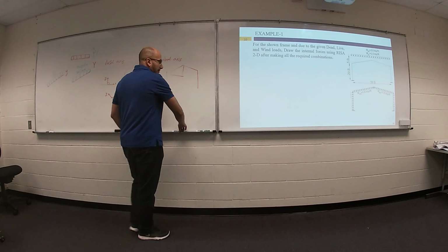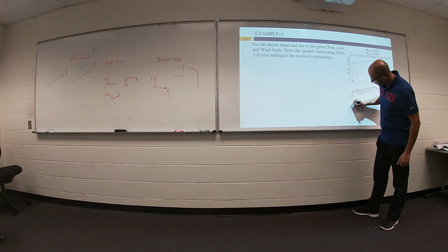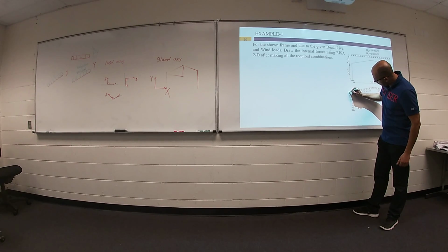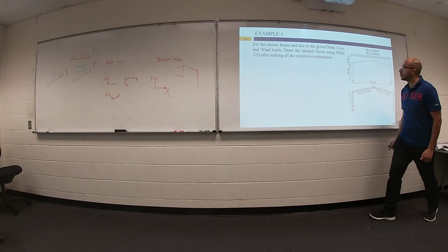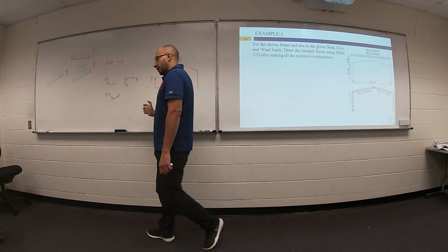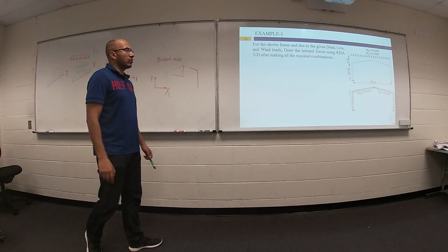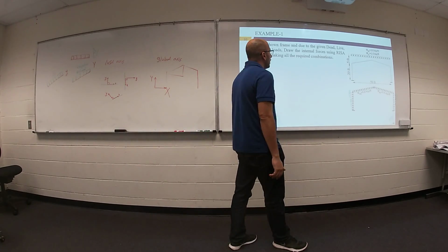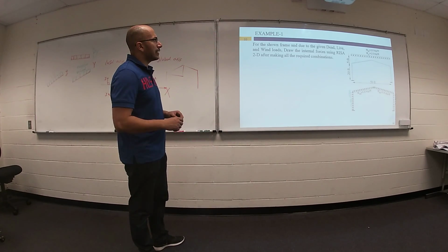Forget it, you can assume this value, 0.5 kip per foot. This 1.6 kip per foot. This value 0.7 kip per foot. Any value. We need to define this in RISA, define your dead load, your live load, your wind load, and make our combination, finally to draw normal, shear and bending moment diagrams.